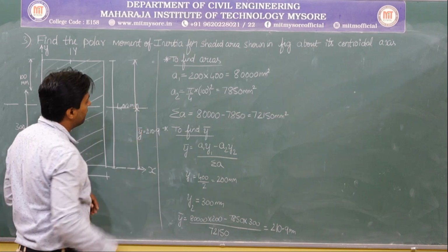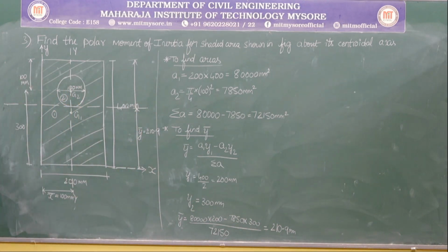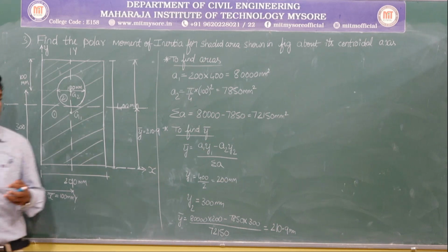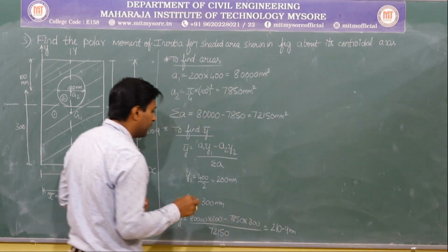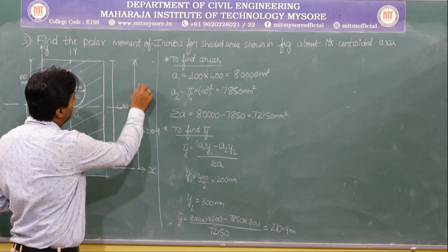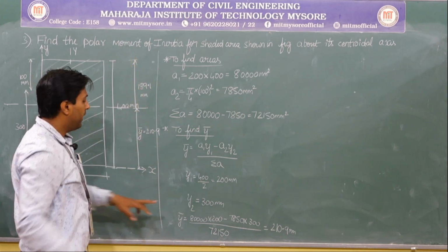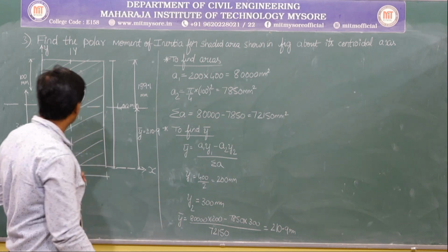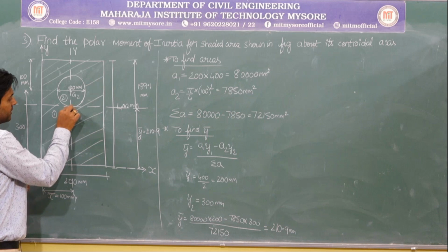So it's 400 minus 210.9, which is 189.1. Right? It's 189.1. Okay. So now I have the x bar value, and now I have the y bar value. Where the two points meet, that particular point is the centroid, capital G.